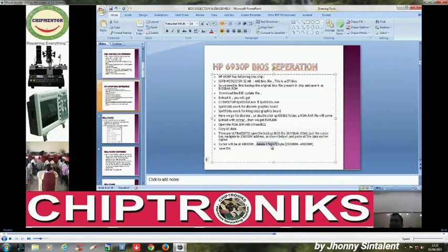So you see, we are using the back.rom file. You know, the rom.bin we have extracted is very less in size as compared to our requirement of a 4 MB BIOS. That means we have to use the original backup to add it and make our system BIOS chip.